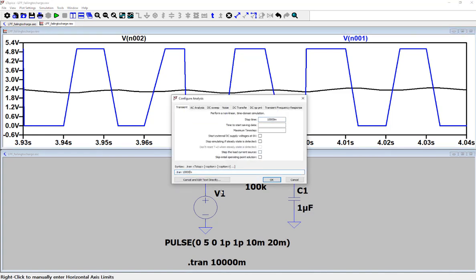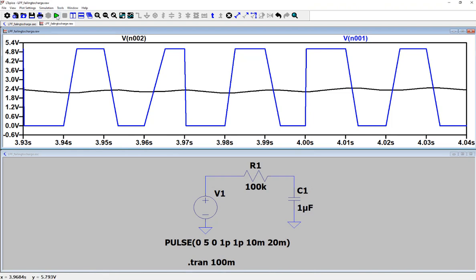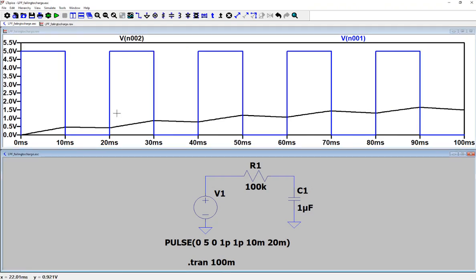Let me show you. Okay, let's look at the input again one more time. So that's the input, and this is a 50% duty cycle. And if you use the low pass filter to filter this 50% digital signal, eventually you are getting a DC voltage, which is in between the two power rails, 0 and 3.3 volts. That's what you get. So input is a digital waveform with a certain duty cycle, and output will be a DC voltage in between that voltage range.